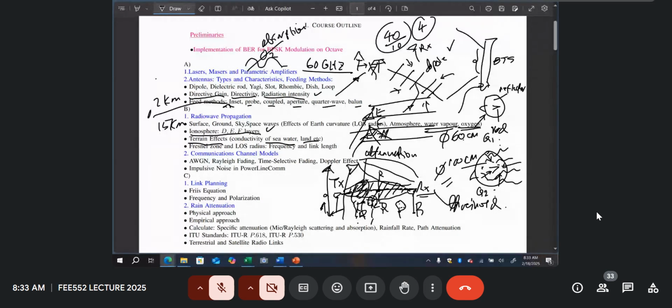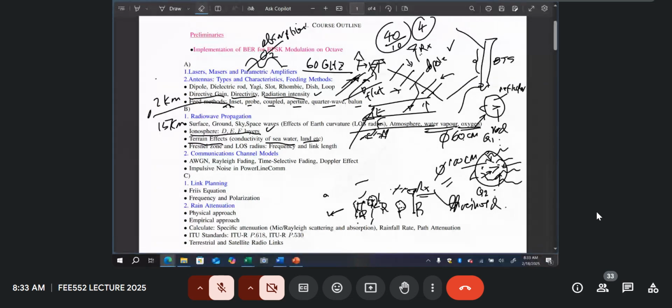So sometimes you go to the field and transmit signals the same distance, and you go to another area with obstacles, then you realize the signal levels that you're receiving on a flat surface are lower, because the signal actually disappears into the environment. But for the ones with the obstacle, they're reflected into the receiver. So sometimes the flat area is worse than a place with hills or, let's say, with obstacles. Again, those are learning areas that we need to see when you are doing your link design.